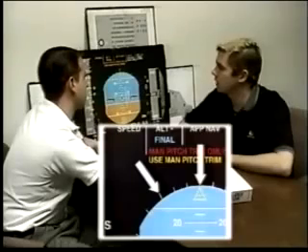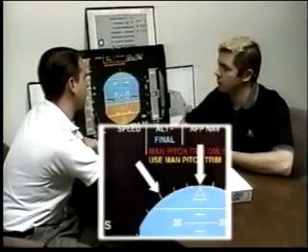Okay, what about a bank angle between 0 and 33? If I'm between 0 and 33 degrees and I'm not in high speed protection, it's going to maintain whatever bank angle I have. Anything that might occur at 33 degrees bank or beyond? Beyond 33 degrees bank, I'm going to lose auto pitch trim. And once I get to 45 degrees, I'm going to lose the autopilots and the flight directors.